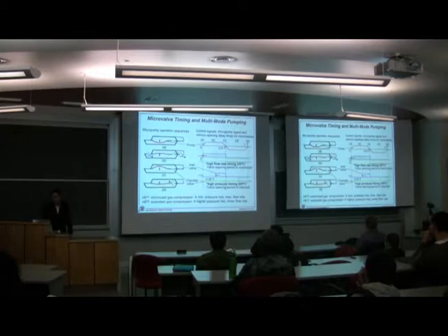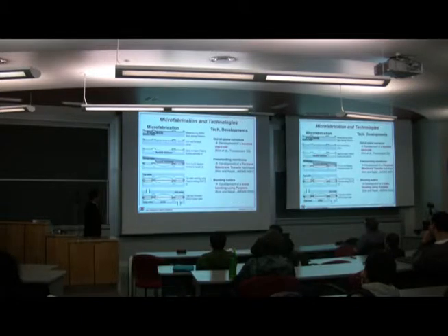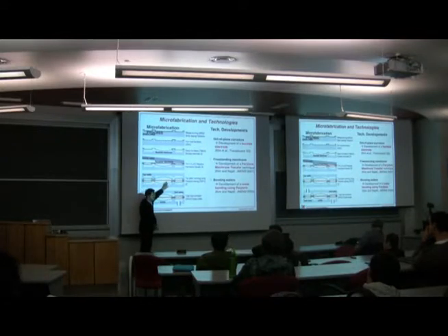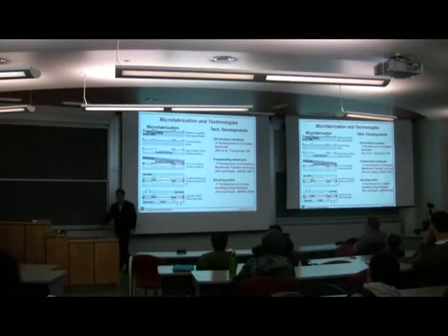So if we can do the control, then we can control this high flow rate and high pressure. So we did the fabrication. This is a wafer. The wafer thickness is 500 micrometers, so two wafers make 1 millimeter, and then you do all this beautiful work, and then build the electrode for electrical conduction, and then there is a membrane moving up and down. There is another membrane which has support so that you can control the flows.